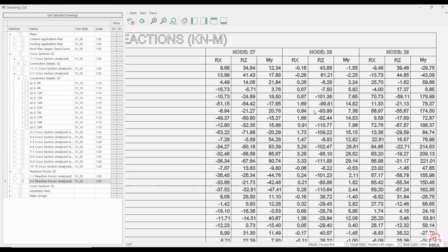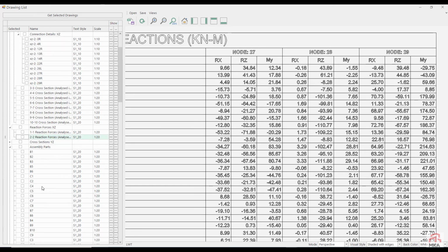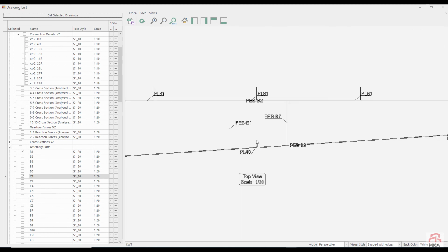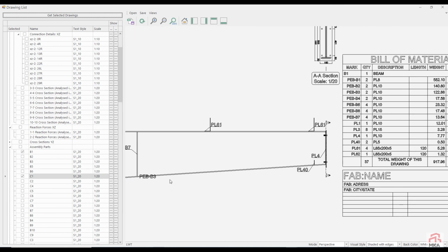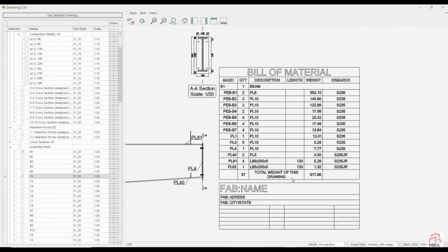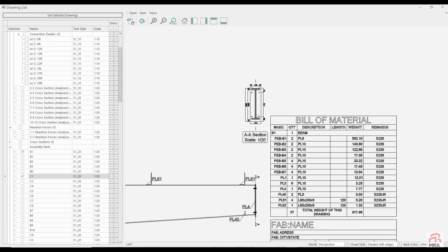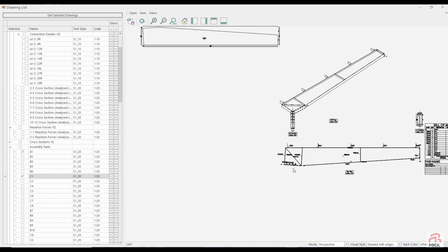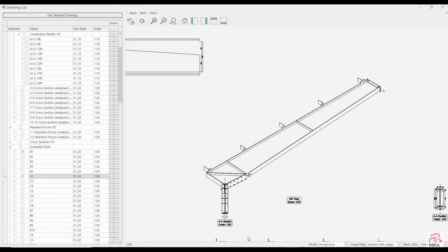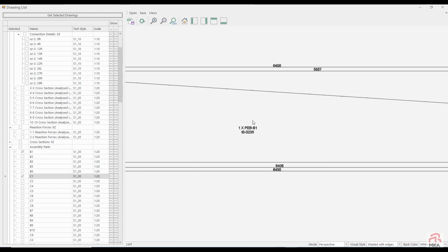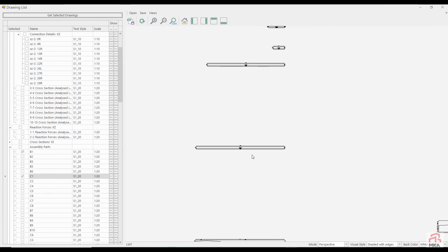Let's look at the drawings of the assembly parts. Let's take the drawings of the assembly part of the B1 and C1 column. This is our beam. The names of the parts used in our beam. Information on which piece to use in which quantity. Detail over there is the detail on the column beam connection. 3-dimensional view of the assembly part. And we can follow the dimensions of the parts that make up the assembly part here.